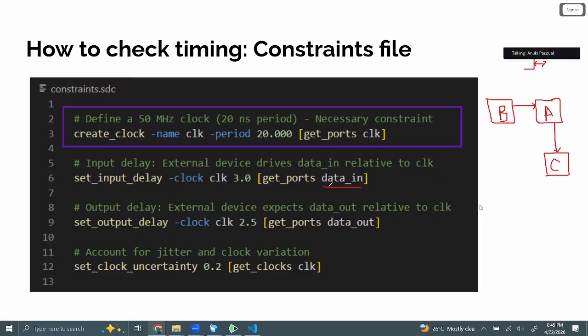So this is only relevant if we are using external devices that use the same clock, like they are all synchronous. It doesn't matter for taking input using buttons or output to LEDs, that kind of thing. So you can ignore it. Timing analysis will give some warnings relevant to these things when we are doing it.